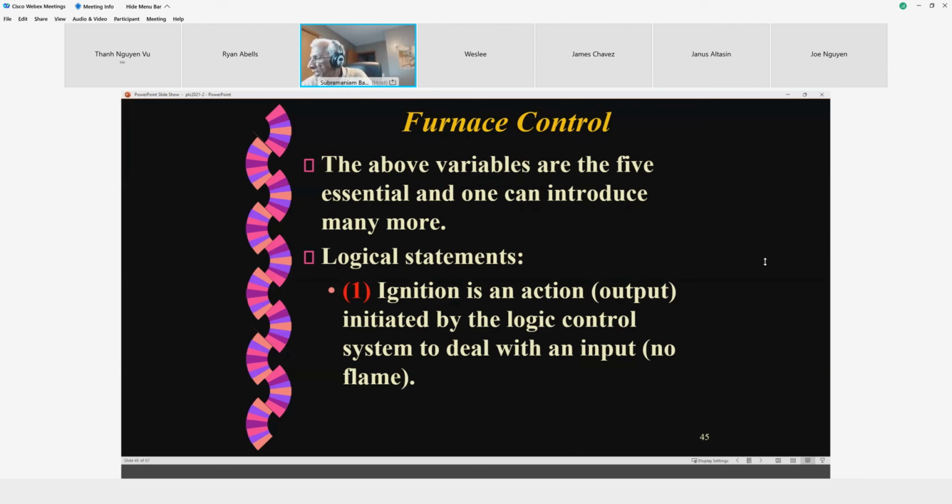And in high efficiency furnaces, I'm saying how you can actually add more inputs and outputs. When there is a flame burning, the byproduct is water. To some extent there is condensation coming out. That has to be pumped out. So you also have a pump, and the pump will have a level sensor, which will push it out when the chamber is full. So more stuff can be added to make the problem more bulletproof, if that's what you want.